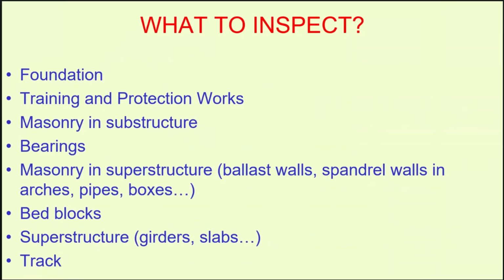Foundation, training and protection work, masonry and substructure, bearing, masonry and superstructure. What are those things? Ballast wall, spindle wall, arches and pipe and boxes, bed blocks, steel girder and slab, track, etc. These are the many items which you need to inspect.